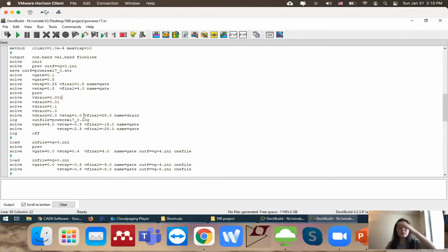And then when it goes to the larger voltage, for sometimes, like for the ID/VD curve, you're going to saturate or something. So it doesn't matter too much if your step is larger. But it is also up to your requirement on the simulation. If you really want the step smaller for the larger voltage, it is okay also that you do the step equal to 0.1 for the drain voltage above 2 volts. It is totally fine.